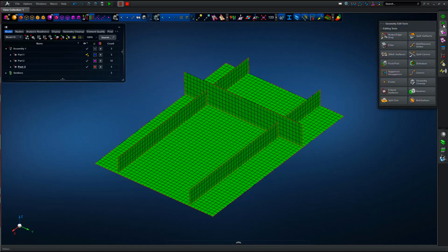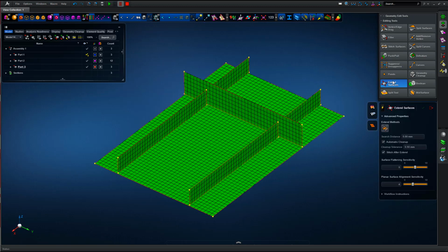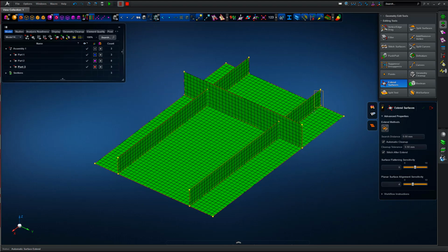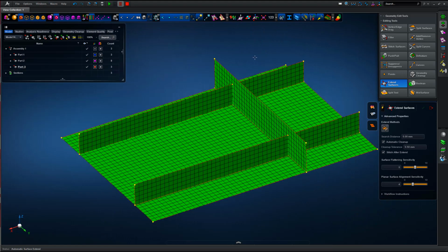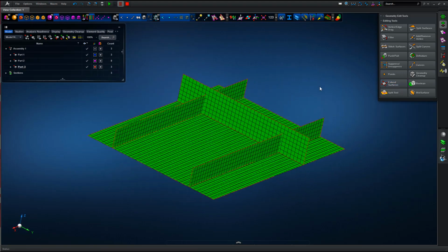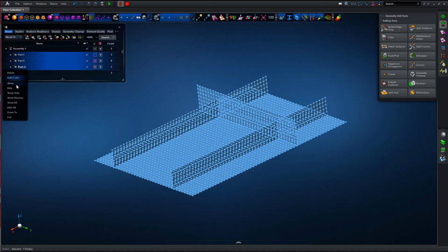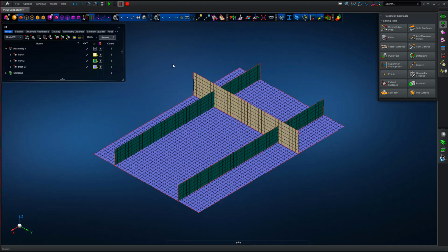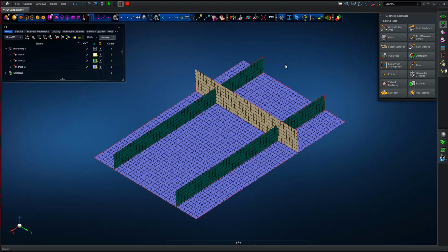Again using the defaults, and now moving into extending, so bridging the gap between all the mid surfaces, again using the defaults for this function, middle mouse button to accept, and all of the surface edges that lie within that 5mm tolerance for snapping edges have snapped together. So we're going to auto color the discrete parts that have been generated, so we can see a distinction between those objects within the full assembly.